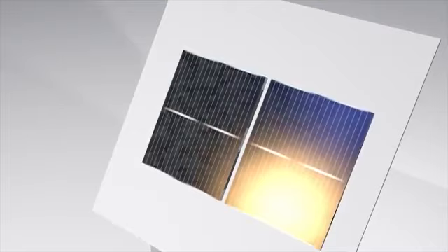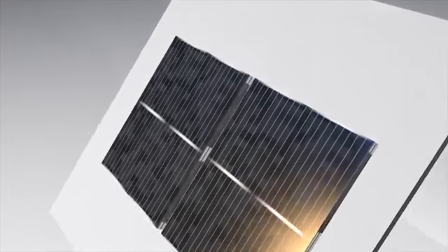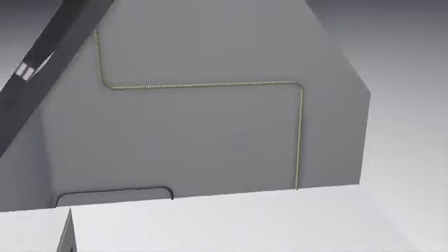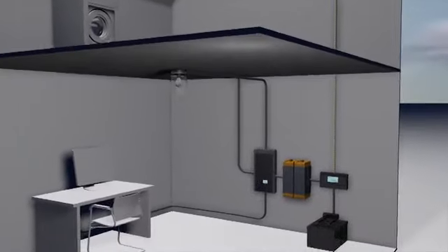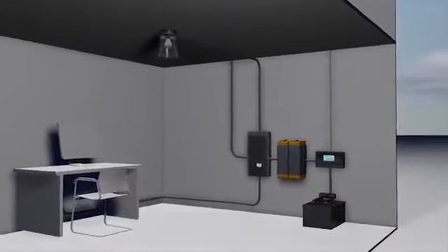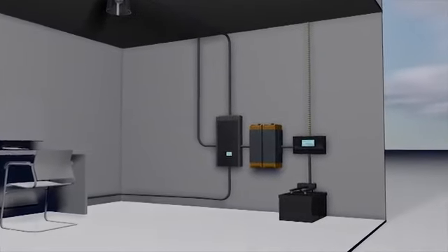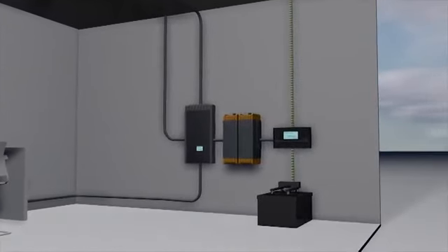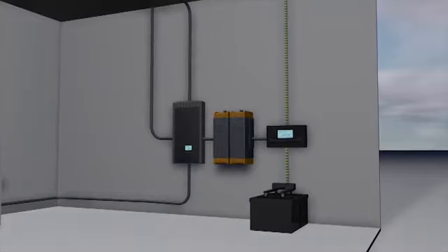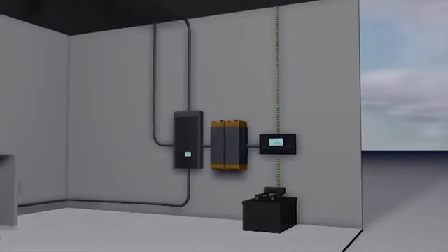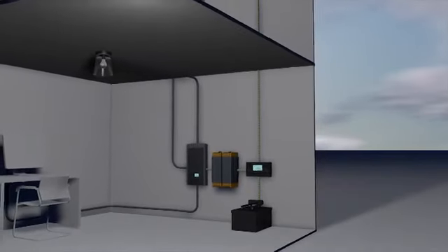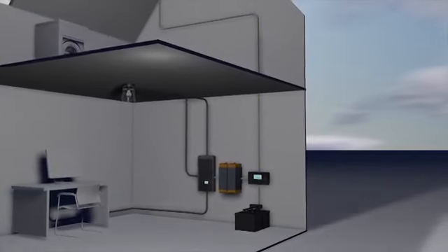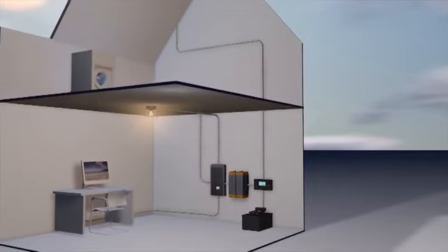On a normal day with the sun out, the PV modules on top of this rooftop are busy converting the incoming irradiance into photo-generated power. The battery is constantly being charged or discharged through the charge controller, depending on the difference between PV supply and load demand. The off-grid or standalone inverter is continuously converting the DC power to AC and supplying this AC power to the loads.